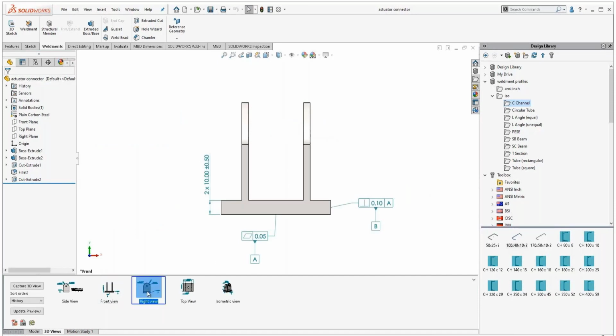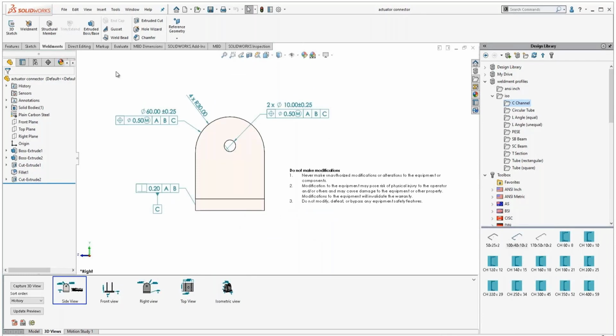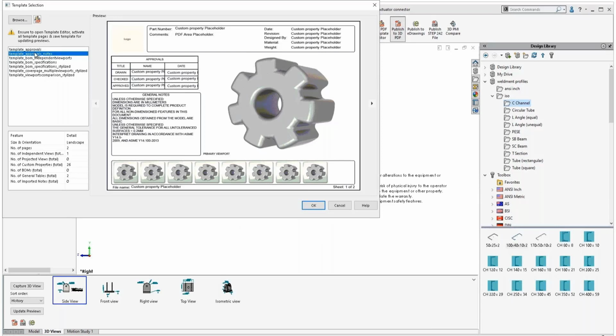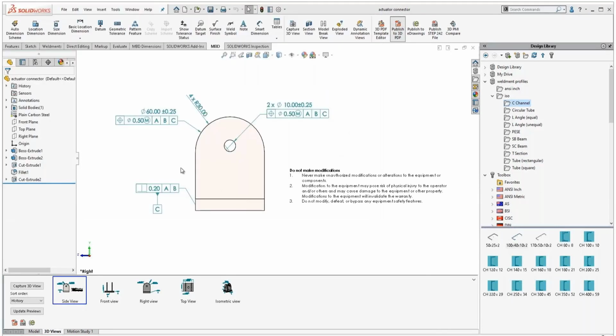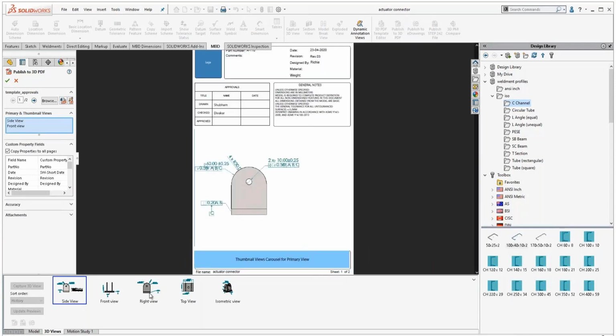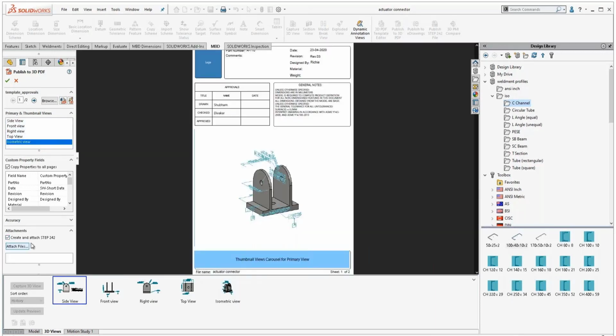The best part here is that SolidWorks has the basic variants of the MBD dimensions, where you can add the dimensions to the 3D model. But along with that, the regular MBD offers you something more than what the MBD dimensions offer. You can extract the particular model or the views which we have captured, the same way we captured in our drawings. Each of the captured views can be exported to a 3D PDF.